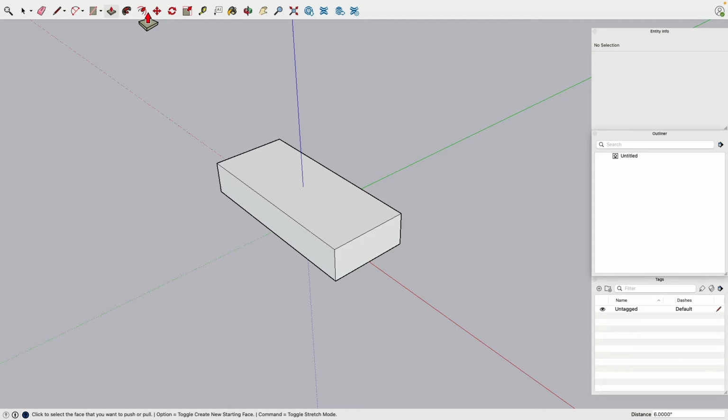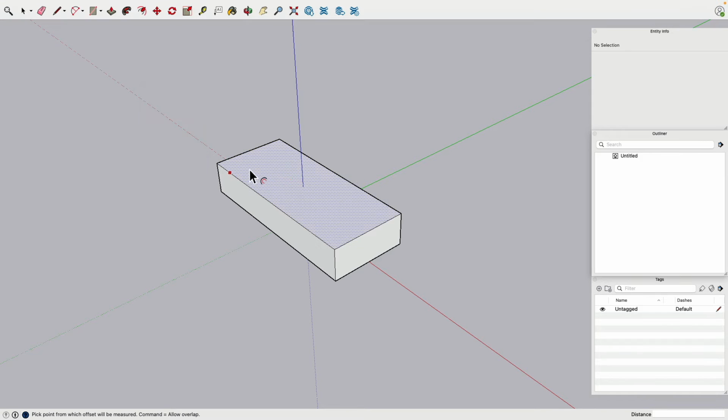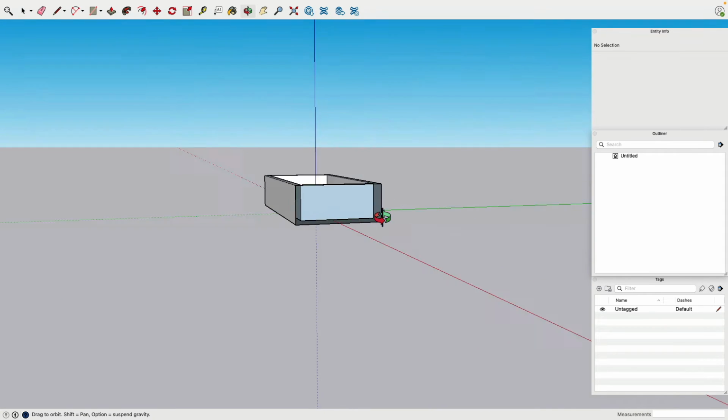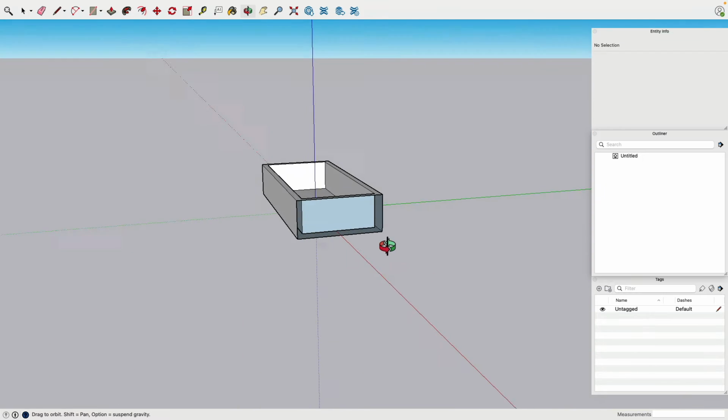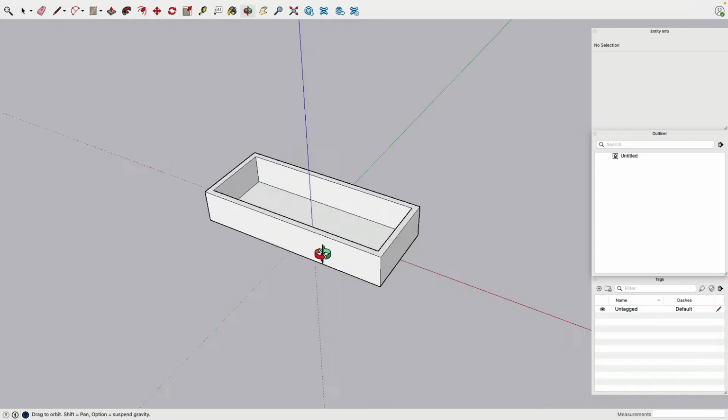It's actually super easy. First, we will go to the offset command, tools, offset, and then we offset by 1 inch. Then we can go to push and pull and push this in 5.5. Cool. So now if we verify this, we can select this face, open it. Yep, there it is perfectly offset. Let's fill this face. Diagonal to remove this line. There we are.